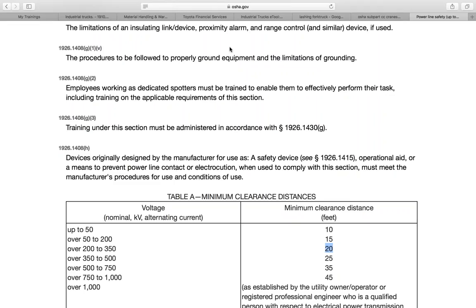Okay, we're definitely going to protect. When we're talking about an outrigger, we're going to talk about protecting. You want to make sure that you're protecting between the superstructure and the outrigger. So if you go back to page 21, when I'm talking about the superstructure and the outrigger, I'm talking about the backside. Do you see where the crane swings? Okay, on page 21 at the top, that Link-Belt. We don't want any employees being pinched. And the most common place to be pinched, and you'll see this, I'll send you some videos on it, is between the cab turning around and spinning and where those outriggers are. Okay, I'm going to send you about two or three videos over the course of tonight and tomorrow that are going to demonstrate all that as well.